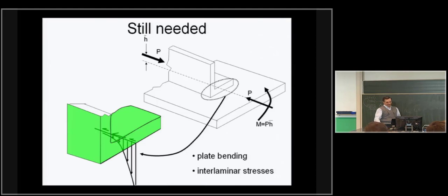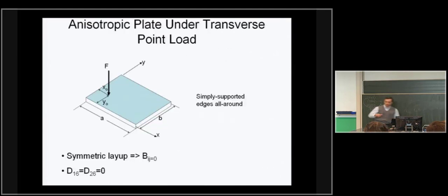But the purpose of this exercise was more to see a complete solution of the governing equations more than anything else, which we did here. But as I'm emphasizing, you need to address also the bending moment and the interlaminar stress issue to complete that design problem. Another case that we will try to solve exactly involves a plate with a point force, a transverse or vertical point force, which can be anywhere acting on this plate.